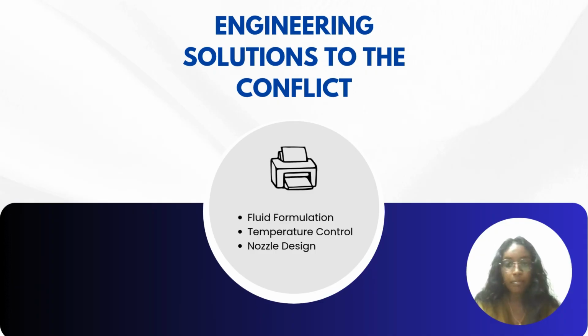Engineers overcome this through several strategies. Firstly, they use specially formulated fluids with surfactants to control viscosity and surface tension. Secondly, they apply slight heating to reduce viscosity without drastically changing surface tension. And thirdly, they design the nozzle geometry to balance flow dynamics with droplet precision.